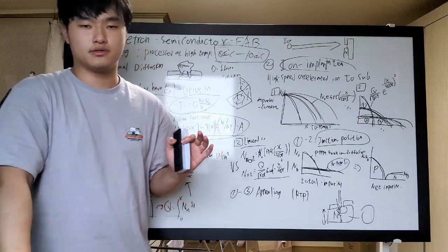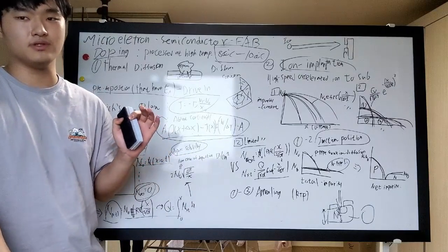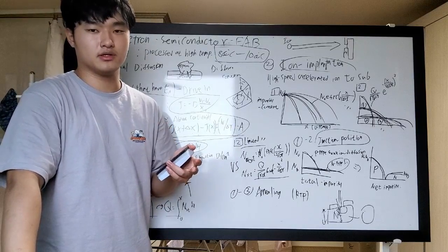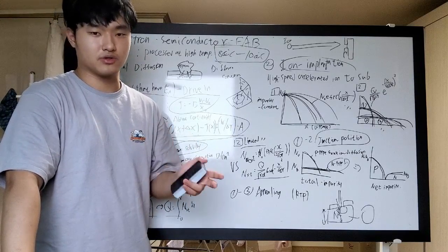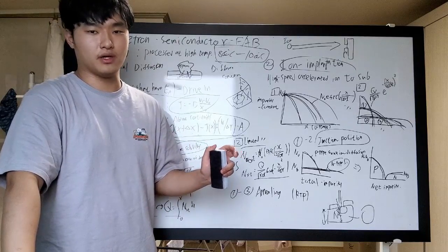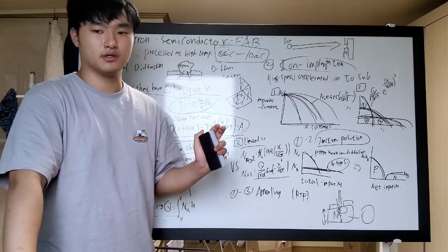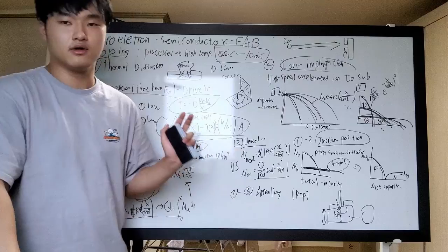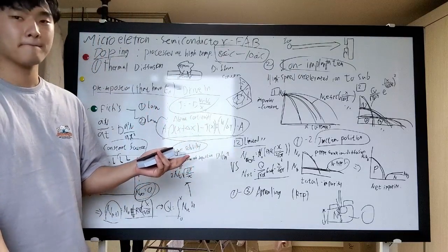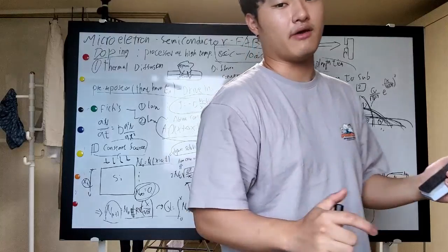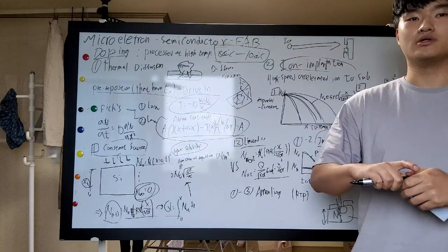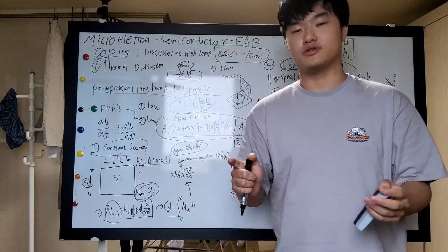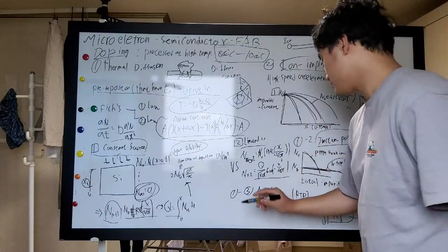Even when the heating process has been ended, let's guess you just boil water for 10 minutes. Now you finish your cooking, but the water will have some remaining heat. Of course, it will not be close to 100, maybe 60 or 50 degrees. So some remaining heat will affect the dopant process, and it will cause unwanted effects, unwanted results. And the thermal budget.